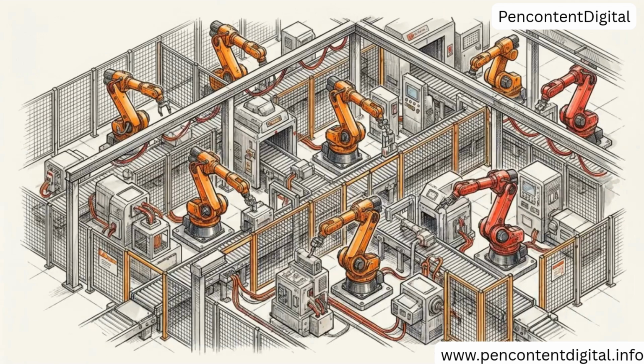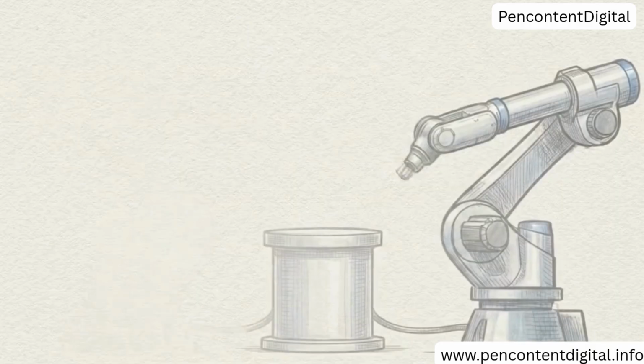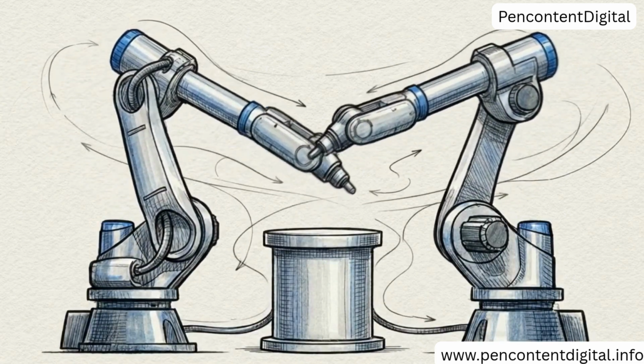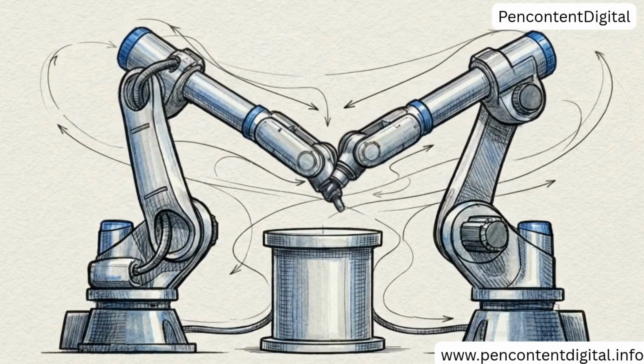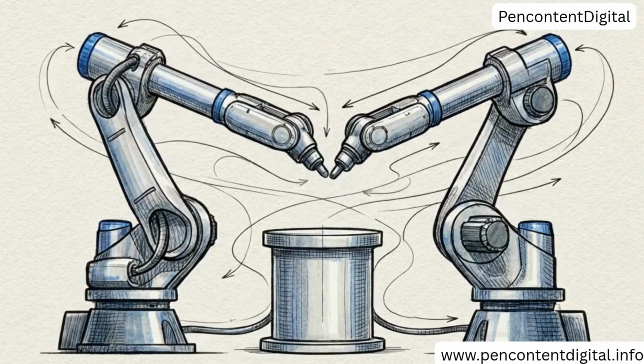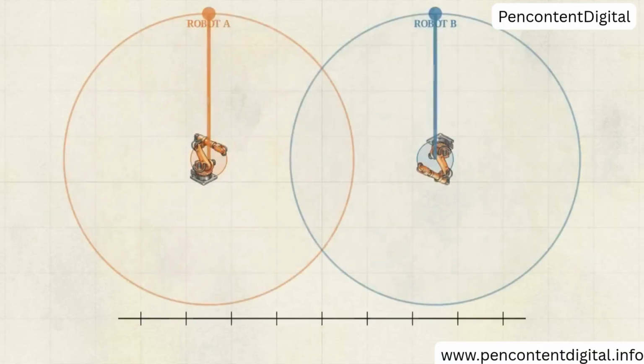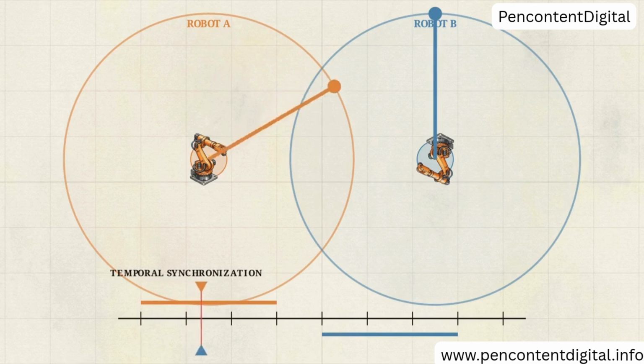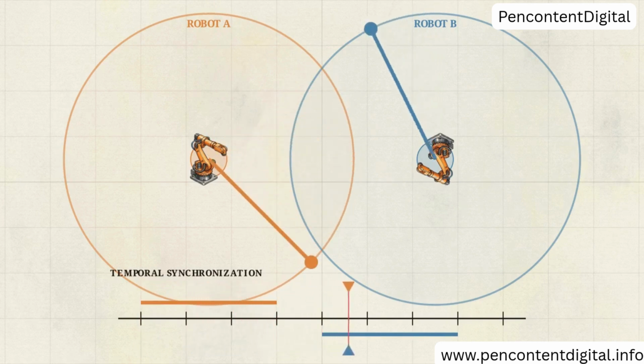This spatial awareness is especially critical when scaling up to multi-robot cells. Operating multiple robotic arms within the same footprint requires extreme spatial synchronization. The arms must weave around each other and the workpiece at high speeds. RoboDK manages these overlapping workspaces, ensuring the timing and positioning of both machines remain synchronized to prevent impacts.